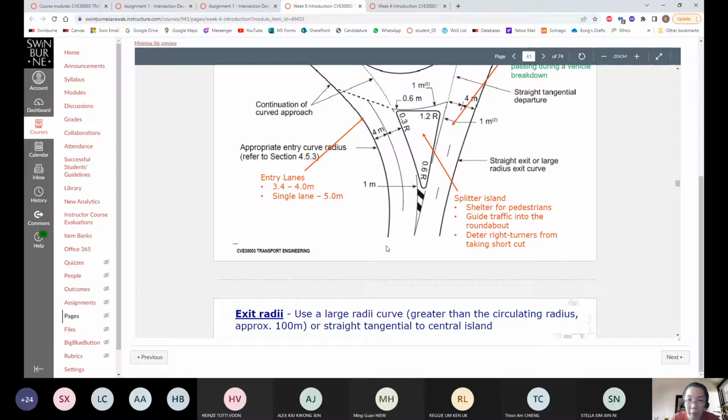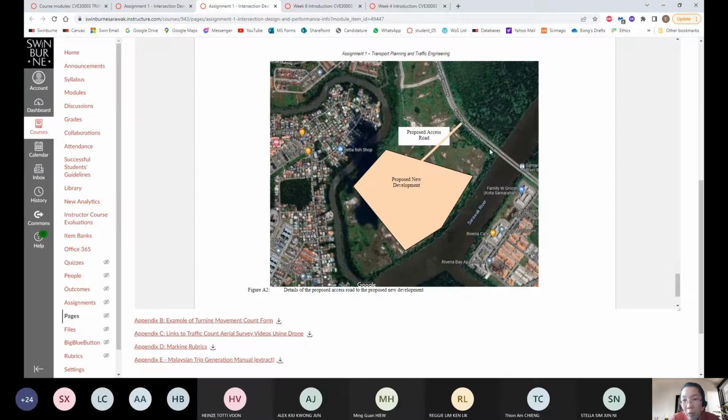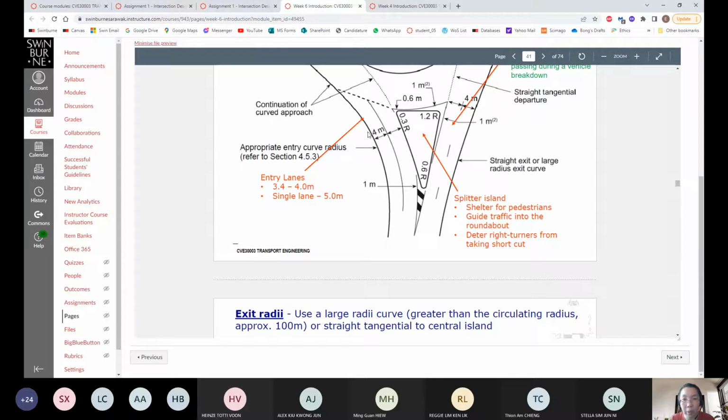So if you have a normal 4-lane 2-way, if I go back to this, and I cut a cross section, I would get 3.5 meter, most likely 3.5, and 3.5 on this side as well. So you get a normal lane width.